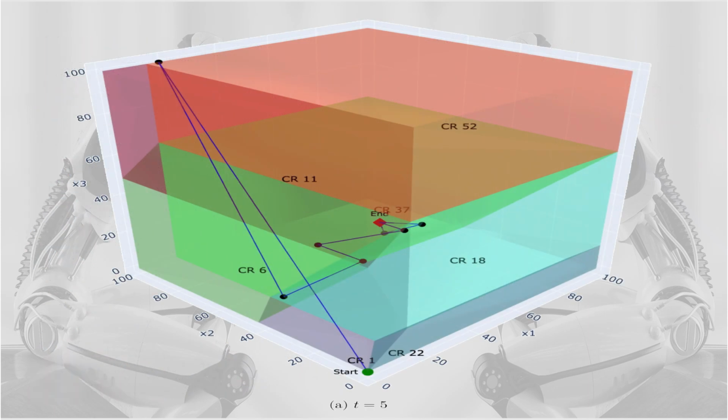When the objective function is linear or quadratic, and the constraints are linear, these regions divide the space of feasible parameters into polytopes, and within each region, the optimal solution is described by an affine function of the parameters. This structure allows for efficient implementation of optimal solution strategies, as the solution reduces to a simple function evaluation once the appropriate critical region is identified.